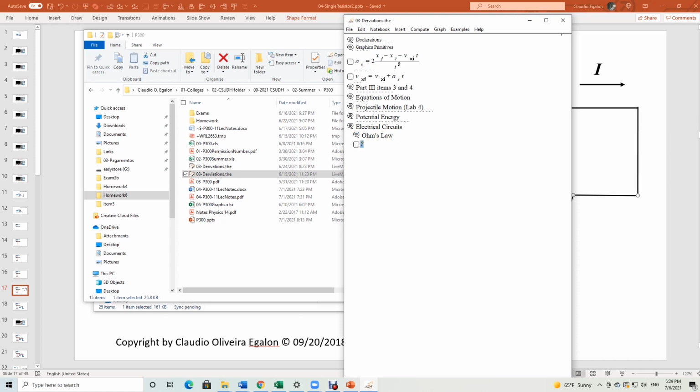So assume that in our case we have a voltage source that's 9 volts, and we have a resistor that's 270 ohms. What do we want to do? Find the current. Given a power source of 9 volts and a resistor in the circuit of 270 ohms, find the current in the circuit. We go ahead, we use Ohm's law. We want to find out this value here, this current.